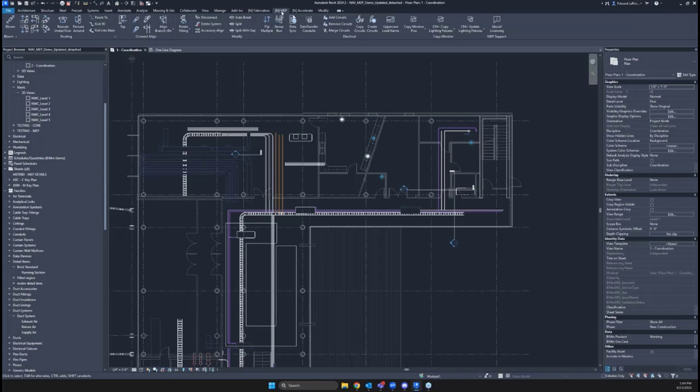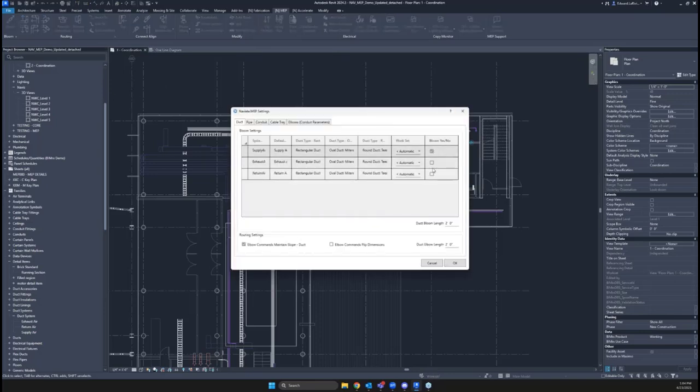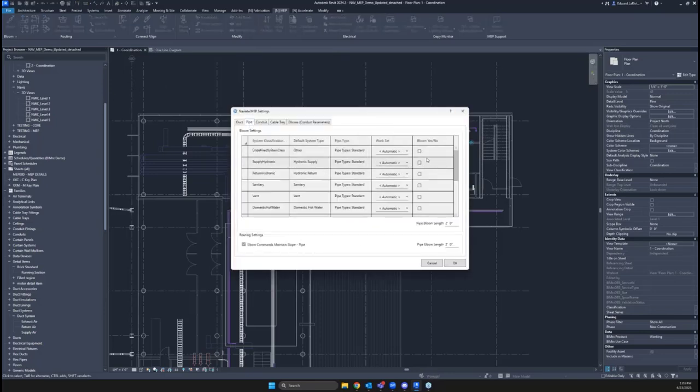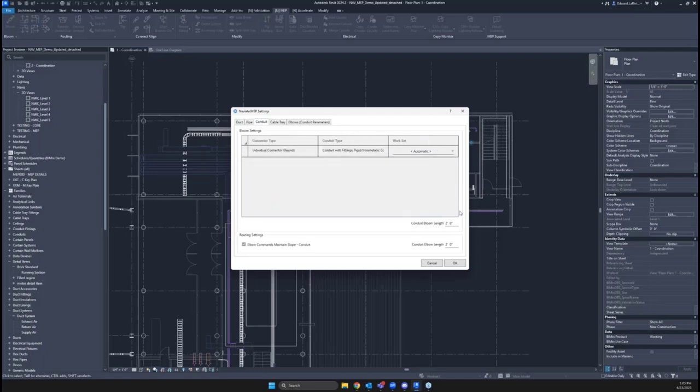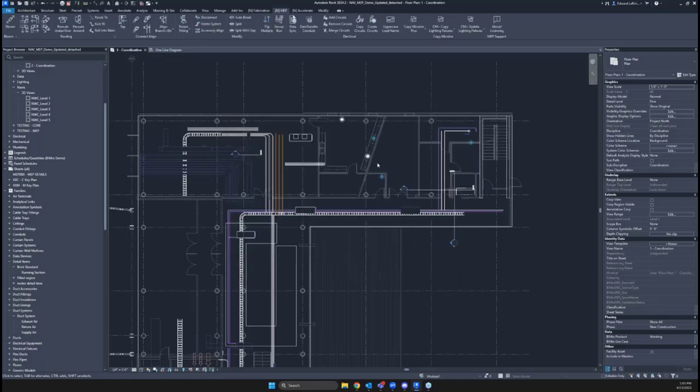When we briefly look inside that ribbon, running from this Bloom tool all the way to the right over here where we see this flip multiple, everything that's sitting up there is actually going to be a routing tool. Now you might briefly be seeing the man behind the mirror. I was doing a little bit of conduit earlier, so just toggling some settings that we'll talk about later. So the far left side is all about modeling, and for any electrician sitting here, the far right side is for you guys. This is all circuiting tools that we'll be going through as well.